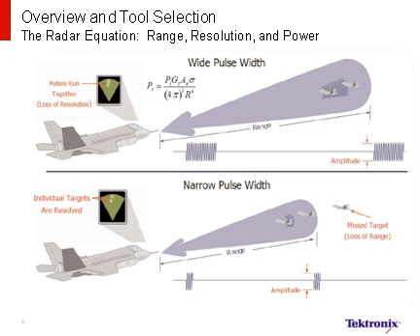In the most basic form, radars use a series of RF pulses that are turned on and off for a short period of time, then on and off again. As the signal travels to the transmit antenna, it then reflects off the target and returns to the radar. The reflected wave is then used by the radar receiver to discriminate the received signal information.